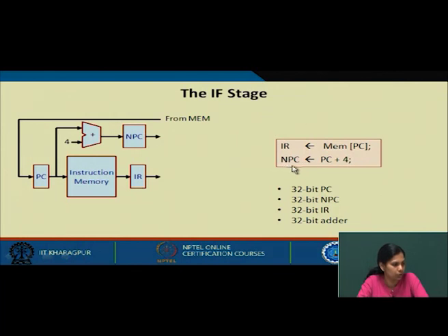For doing so, we require a 32-bit PC, a 32-bit NPC, a 32-bit instruction register, and of course a 32-bit adder.